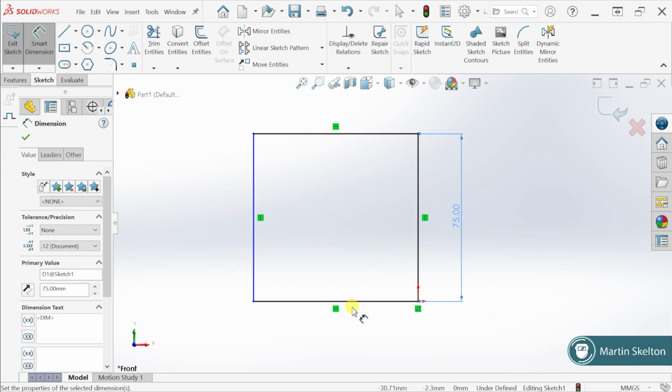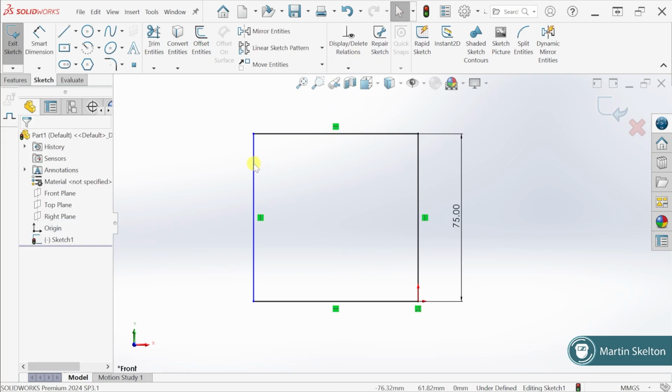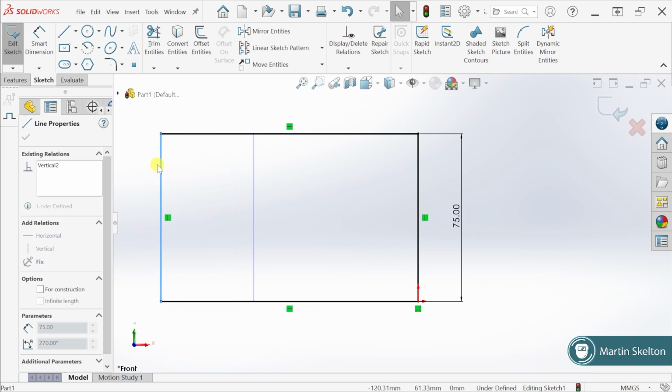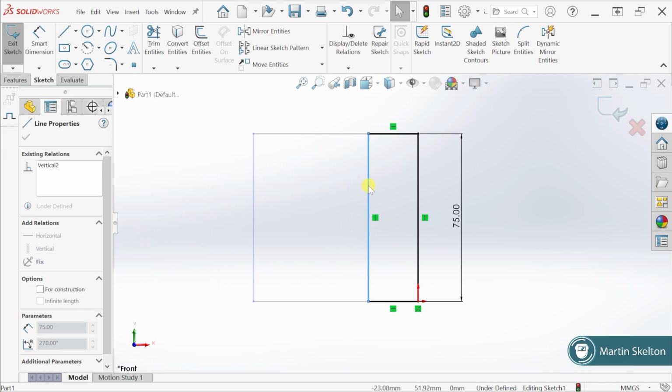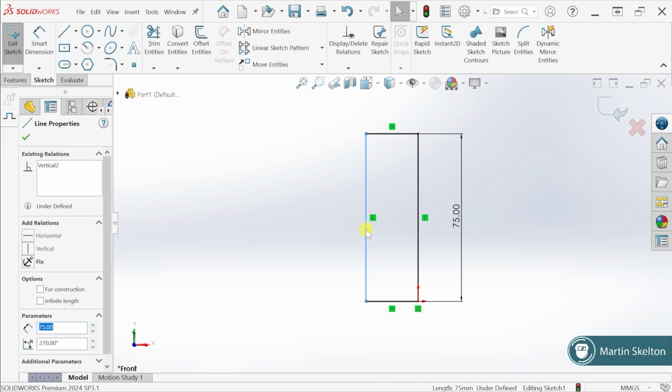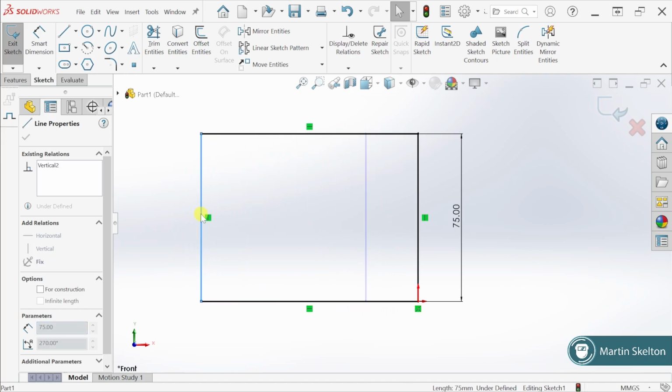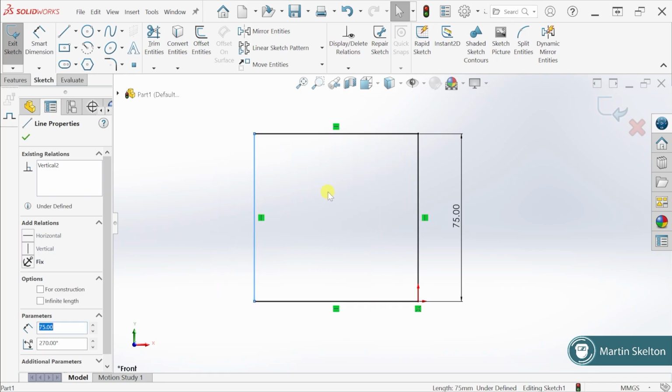What happens when the sketch is underdefined? This is what I am highlighting so much about full definition for. If I take my cursor here and I click my blue line, click and hold, I can drag my blue line back and forth. Otherwise, I can move the size of the box. Well, you can imagine if you had a very precise drawing and you're doing some little piece of it and you touch that line and it moved back 1/4 millimeter.